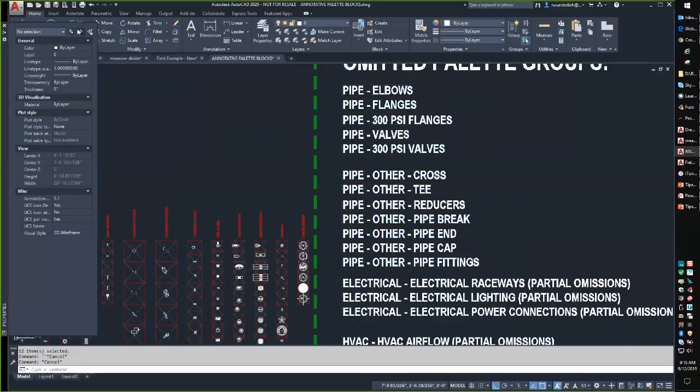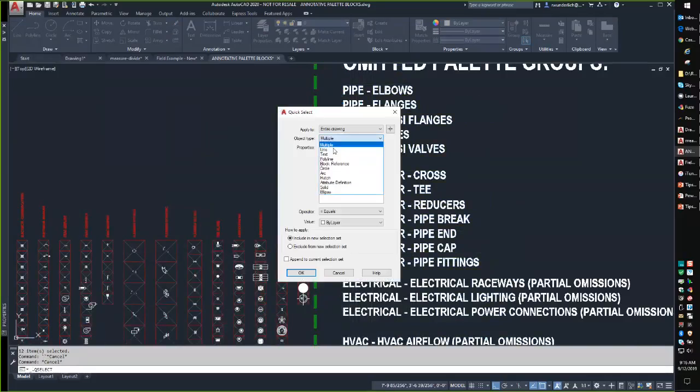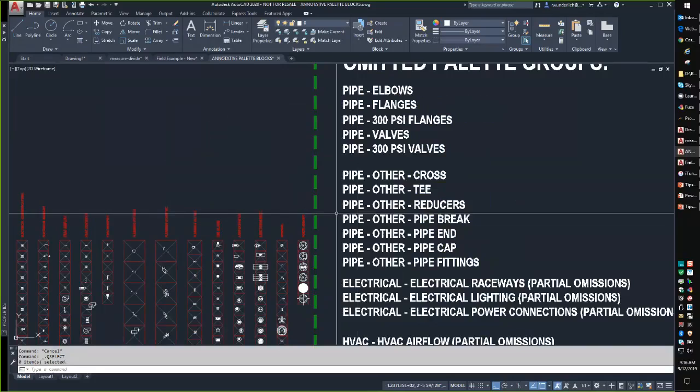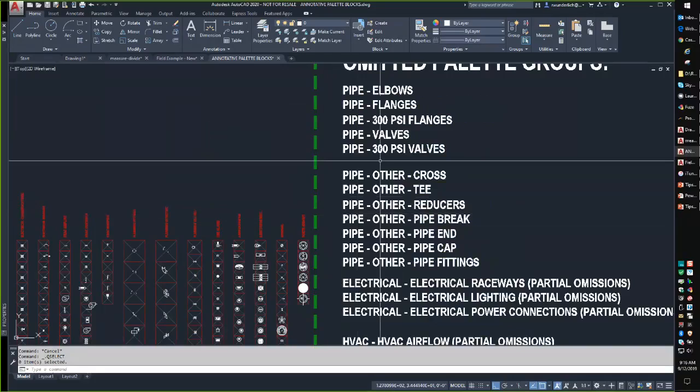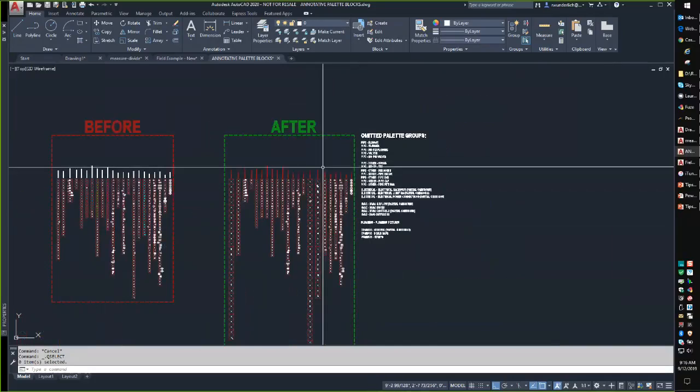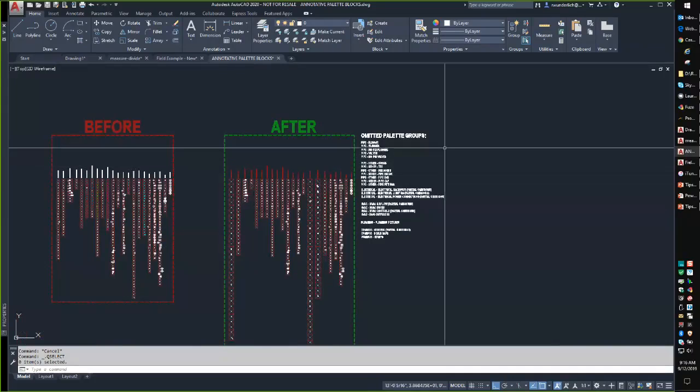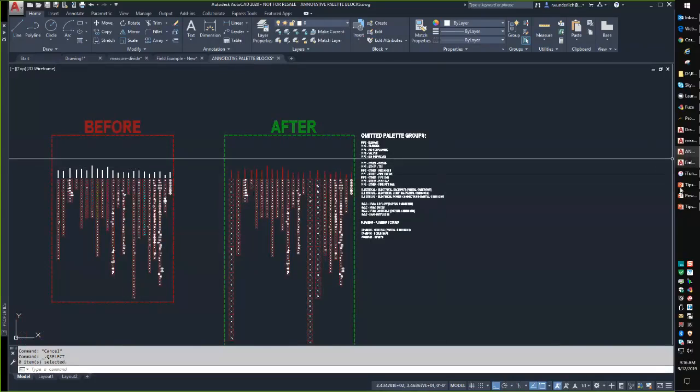We go back here, and we're going to go back to text, contents, wildcard match, star, pipe, star, lowercase, and you'll see it does not pick those. Those are case sensitive under the wildcard match. So that's something to be aware of, and thank you very much, Frank. So that's all about QSelect.